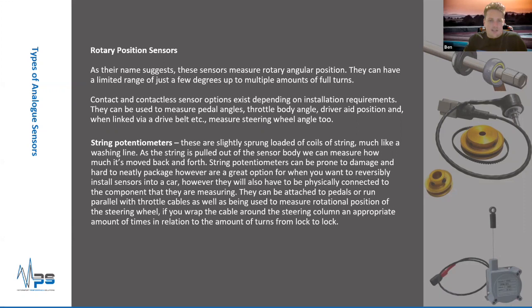So string potentiometers are a bit like a retractable washing line or airline. All it basically does is track the string's movement. It's slightly under tension, so it tries to return. So you could use these to follow a pedal throughout its movement, as long as it doesn't block your foot.